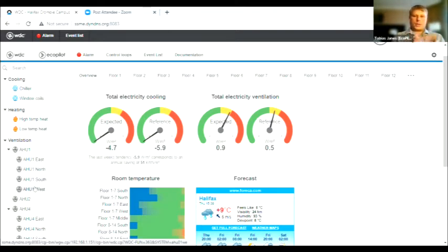And again, this is touching on what Nick said, prepare the building for all of those dynamic factors that are coming up, which is solar radiation, wind speed, precipitation, occupancy, outside air temperature, thermodynamic properties of the building. So how much energy can be stored in the space and how quickly will that energy dissipate out of the space. So calculating all of that, every 2 minutes, we send those offsets to prepare the building for what's about to happen, and in turn, create a more comfortable environment and save energy. In this case, I think the slide showed 24 or 25% on their heating and cooling ventilation needs in the building. So pretty good savings.